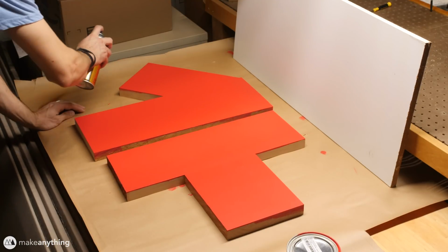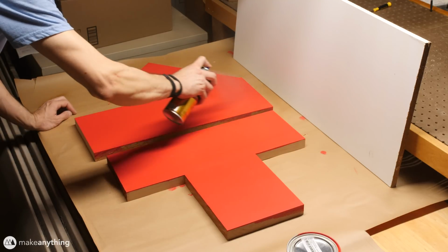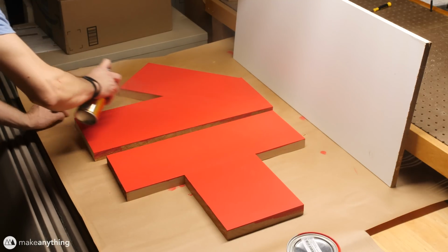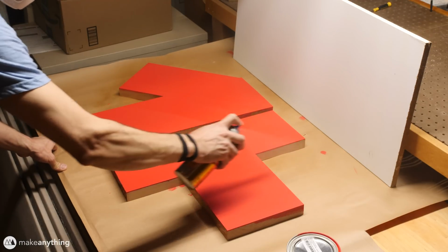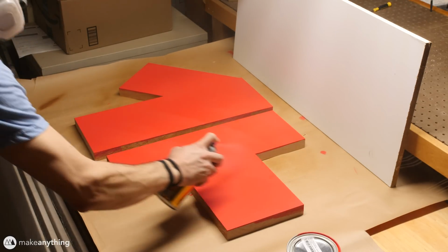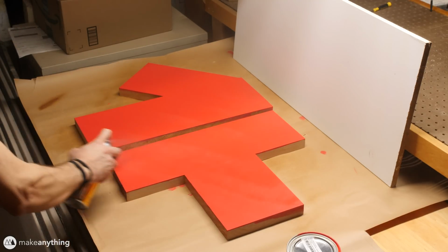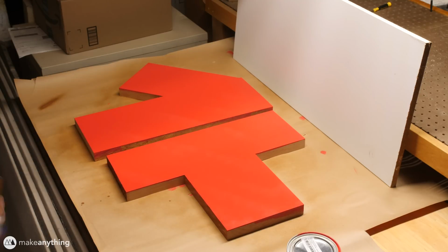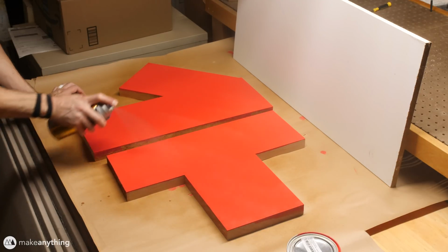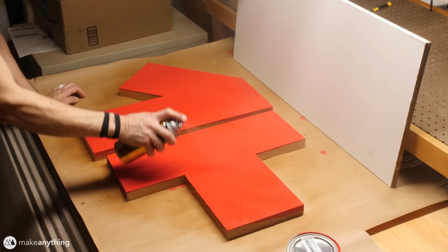And after that's all dry, I'm gonna go ahead and go over it with some spray polyurethane. I'll be applying more of this stuff once the number is completely done, but this coat here is specifically for the purpose of getting a cleaner cut on the CNC. Since this is a latex paint, it's a bit rubbery, a bit stretchy, so by putting this polyurethane coat on top, it'll get a little harder and more brittle, and therefore when I cut into it with the CNC, it should give me a cleaner cut.